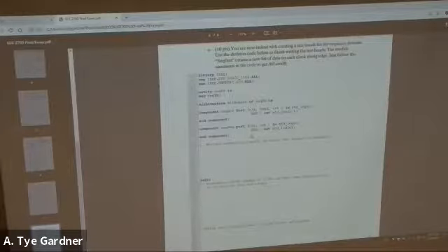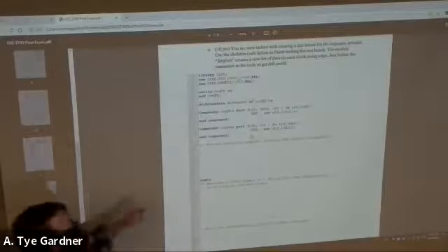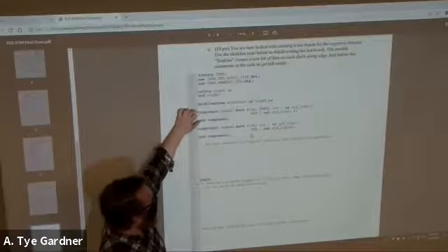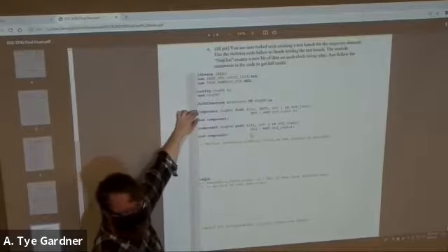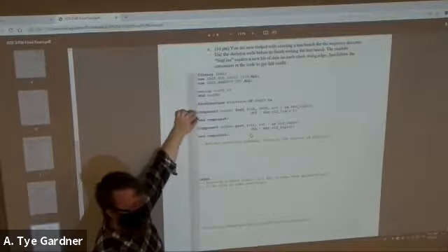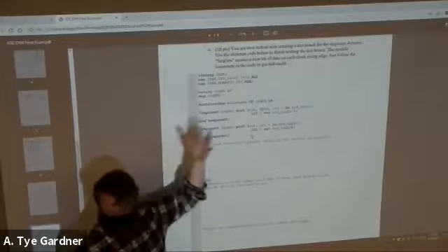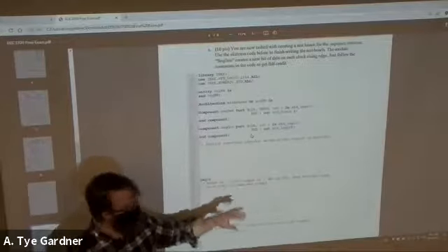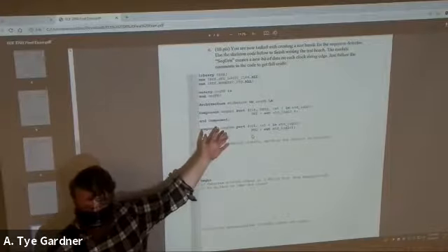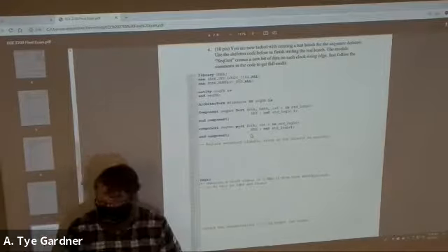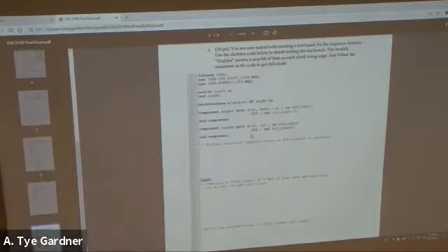Yes, delay. So the clock is both asserting new data for the sequence generator and trying to clock it in at the same time. If there is a difference in delay path, or what we call clock jitter, right? If there's real world problems in this, we don't know what we're getting generated. There's a race condition. There's a real error there. Okay, that was the final exam from last semester. It'll look something like that.